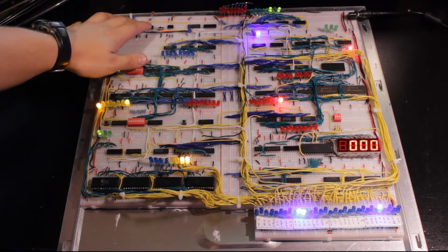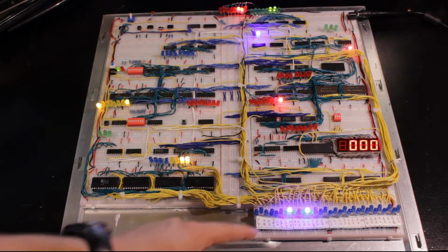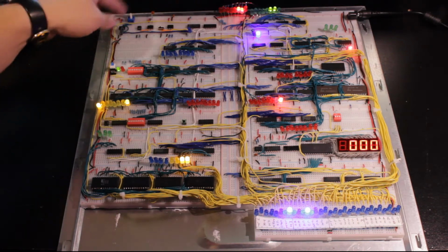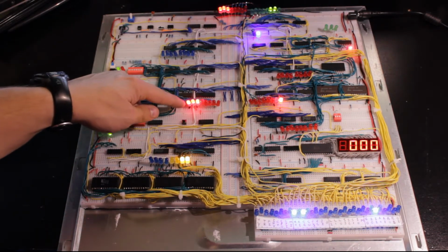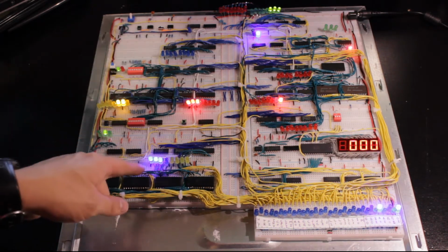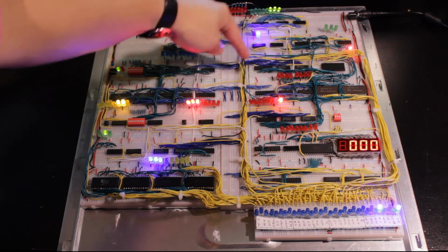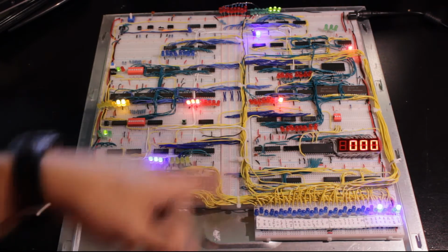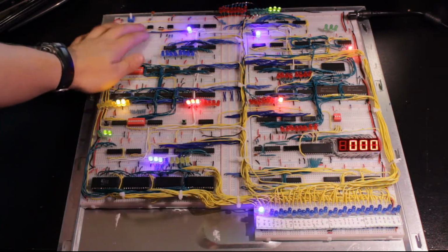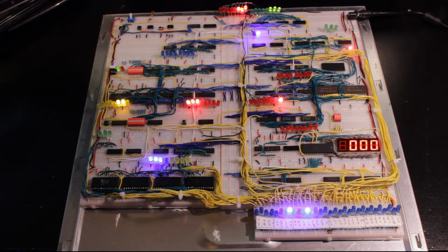So the next thing that's going to happen is the early termination. And now we're back to a fetch cycle for the next instruction. So we're going to take this 6 from the counter, output it onto the bus, get it in the memory address register, fetch the instruction, the 0xE0 for output. That's going to go into the instruction register. Now we're executing the output instruction, which is simply going to take the value from A, output it to the bus, which is 0, so not very exciting, and then take it into the output register here, where we're going to be able to see its output on the display, which is, again, a 0. So we don't see anything remotely interesting that time.